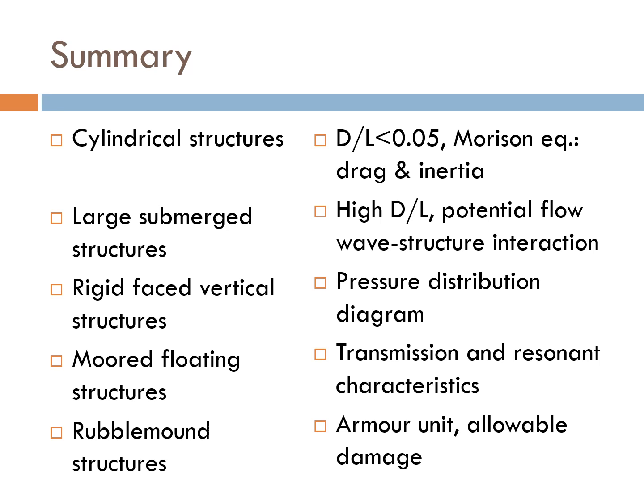For rigid vertical structures, our main concern is the pressure distribution on the sea side of the structure, and so from there we are able to determine the net force and moment acting on the structures, and where the pressure distribution is also important on the lee side, then it also needs to be taken into consideration.